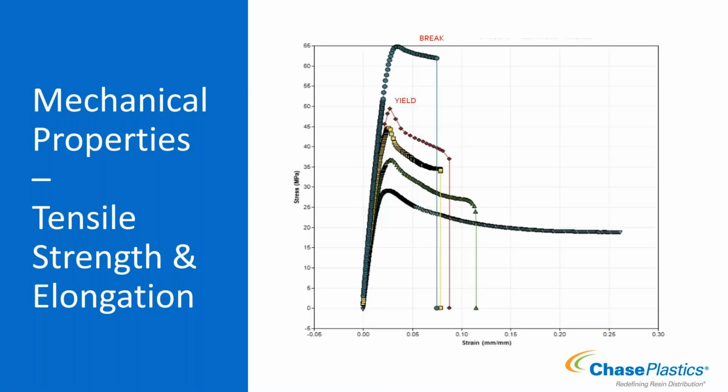Okay. And then on a graph, if you've seen a tensile stress strain graph, it would look something like this. Your yield point is going to be right here, where you don't see an increase in your stress as you continue to pull. So this is your yield point, they're at different temperatures, I believe. And then your break, where it finally breaks apart, and there's no more value to be given. You broke the part. So that's the stress strain curve compared to the actual testing apparatus.